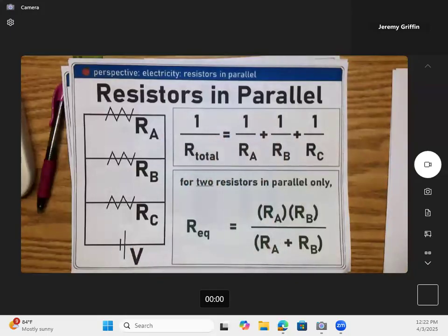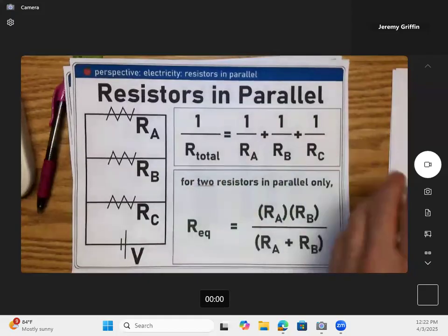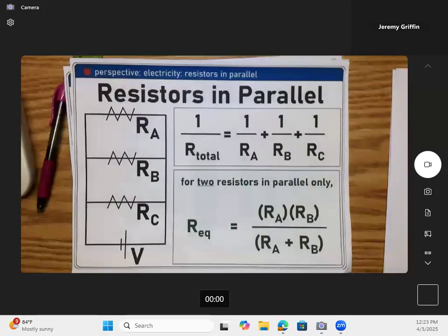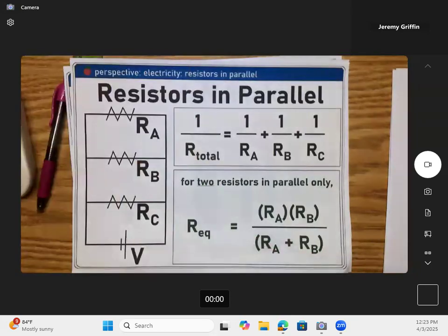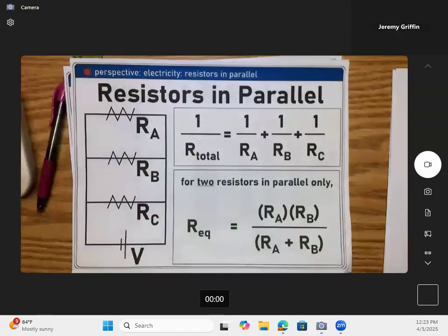Okay. And hang on a minute. Isn't this exactly the same math as a bunch of people working together in a team to complete a project, and how much time it would take? How about painting a fence? It takes Alan some time to paint a fence, and Bob some time, and then Chad some time, and so on. Derek, Eric, and Ferret. Can you do 1 over plus 1 over? So you can do that. It's the same outcome, isn't it? So how about this? If you have more and more resistors in parallel, what happens to the overall resistance? More or less? It's less. Exactly the same as if you have more and more friends painting the fence, it takes less time to paint the fence, doesn't it? It's the same math.